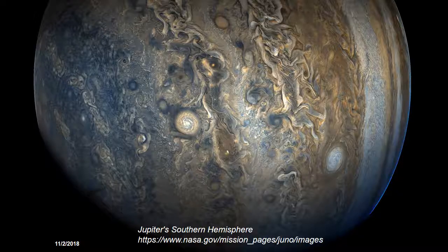Okay, so this is a picture of Jupiter's southern hemisphere. Prior studies have shown that these devices are pretty hard to a TID of about 10 megarad and possibly higher. And so that's sufficient for Earth's radiation environment. But with future plans to go to Jupiter and other high radiation environments, they're going to require that electronics are able to be rad hard up to 10 megarad or 20 megarad to be able to withstand these kinds of doses for an extended period of time.